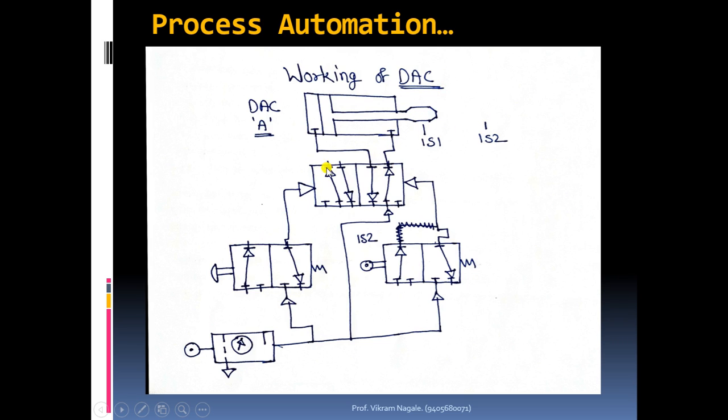What I mean is, whenever this block is in connection with the cylinder ports, the air coming to port 1 of the valve casing has to come inside the cylinder from the left side port, and the air present on the other side has to exhaust into the atmosphere.